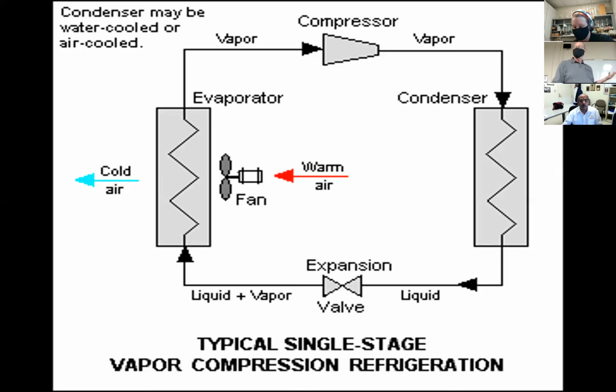The compressor, how much vapor can that compressor handle in a given amount of time? Then you get over to the condenser. And if you've got low heat removal vapor versus a lot of high heat removal vapor, it'll be a different amount that'll flow through. So that's why we couldn't just change from one refrigerant to another. It just didn't work that way.